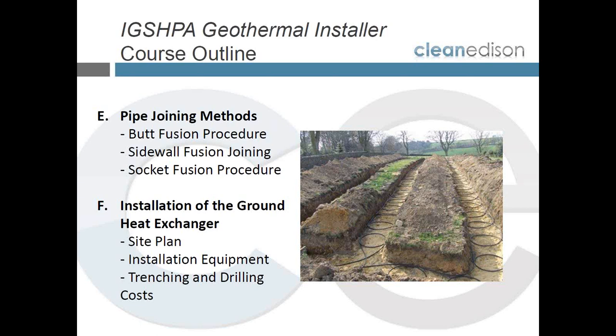Generally, a house can be served by a geothermal system that does not require any socket fusion, but if it is a commercial building and a larger field is installed, then we go through the fusion process. Also, when well drillers drill their boreholes, they generally heat fuse a 90-degree elbow about 4 feet underneath the grass surface and connect it into the house.